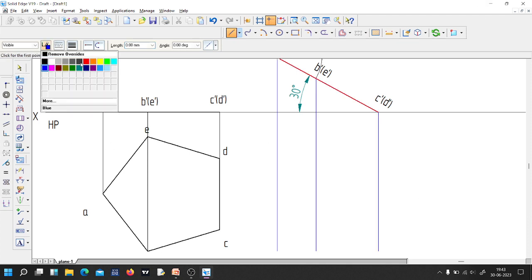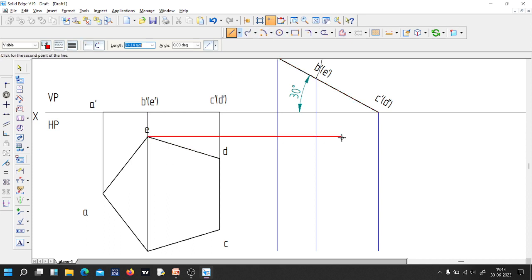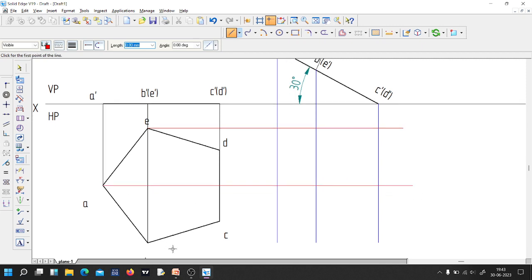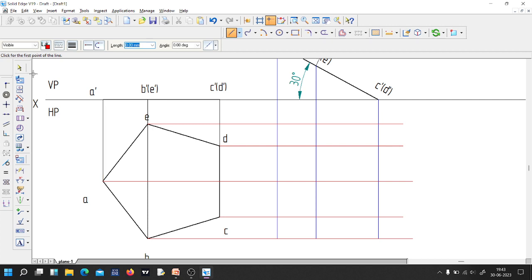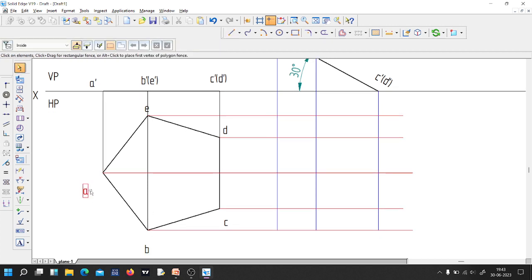Now similarly you project from the horizontal line, sorry, from the top view. So now as you need to place the reference points here, this is reference point A. To copy this one onto the right side drawing, you just hold down the control button and move your cursor.